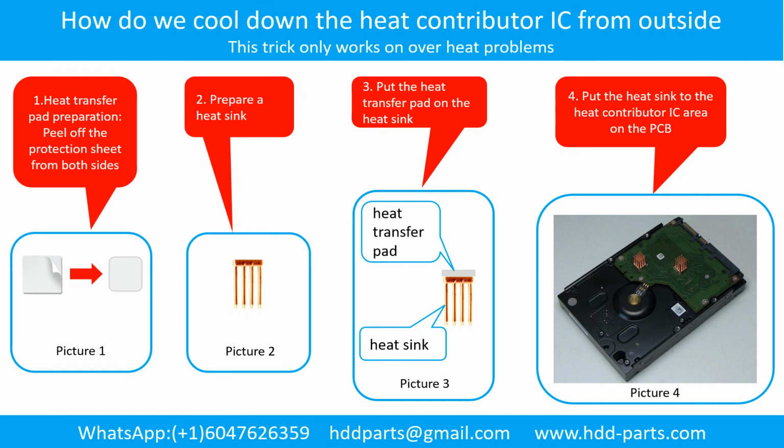Step 1. Heat transfer pad preparation. Peel off the protection sheet from both sides of the heat transfer pad, like picture 1 shows. Step 2. Prepare a heat sink, like picture 2 shows. Step 3. Put the heat transfer pad onto the heat sink, like picture 3 shows. Step 4. Put the heat sink on the heat contributor IC area on the PCB, like picture 4 shows.